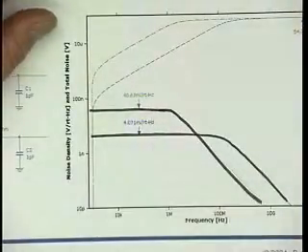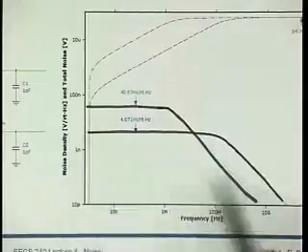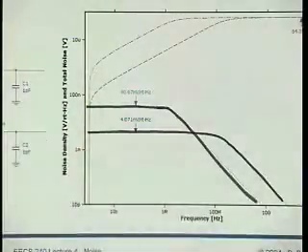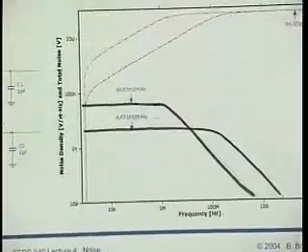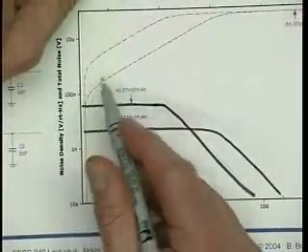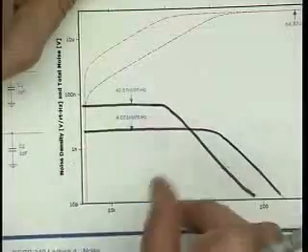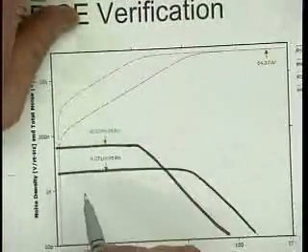And the integrals are the area under these two curves. That's what you're computing. And the area under these two curves, well, you can't judge it here because it's a log-log plot. We always make that error. But anyway, our math tells us the area is the same. So when I run this with SPICE, I usually use the post-processor to simply integrate the noise as a function of frequency. So these are these noise integrals.